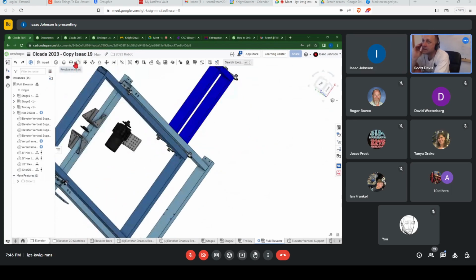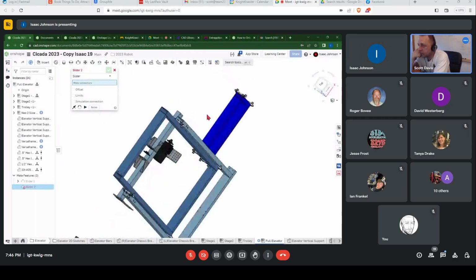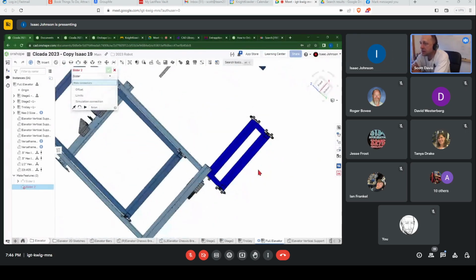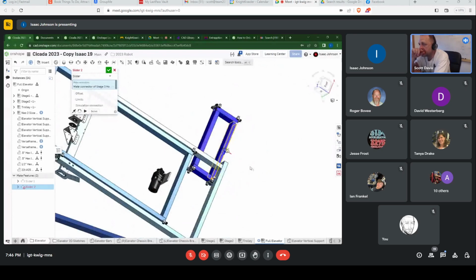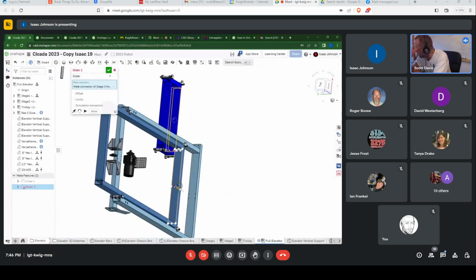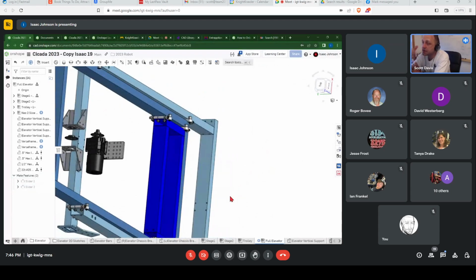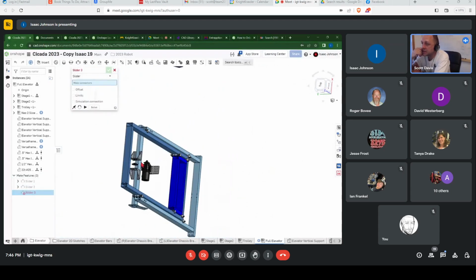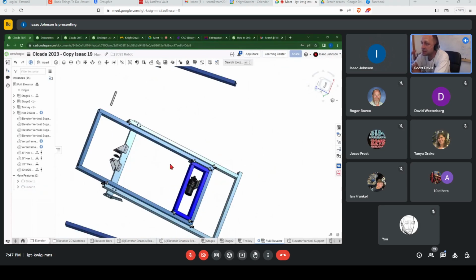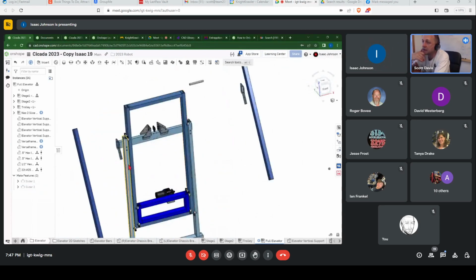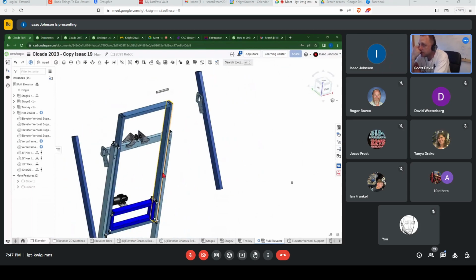Boy, that's really hard to see. But the point is that it's easiest if you put your mates in the line that you want them to travel, right? That's what you're trying to demonstrate? Yeah. So in this case, the bottom face of the elevators made it really easy to get them to slide in the right orientation you wanted. Now you have to constrain them.